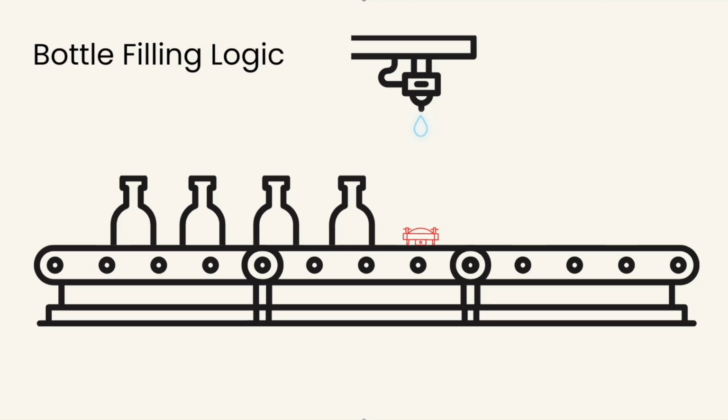So today we'll combine three different types of timers, T-on, TP, and T-off, to create a realistic filling cycle with three stages: waiting at the start, filling in the middle, and waiting at the end before the conveyor moves.